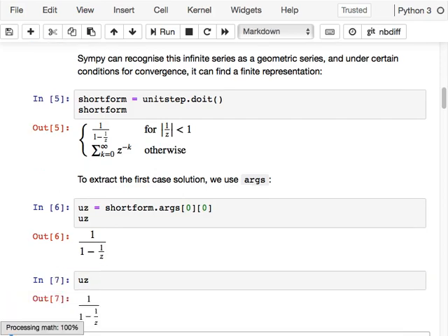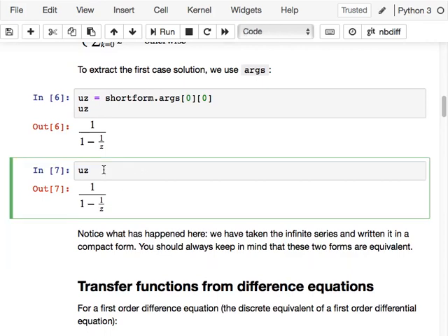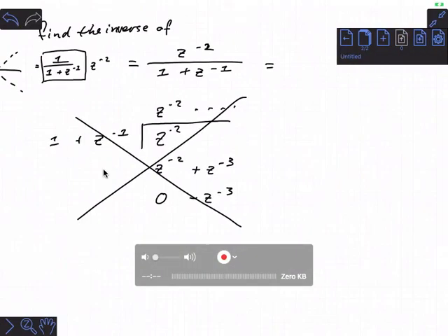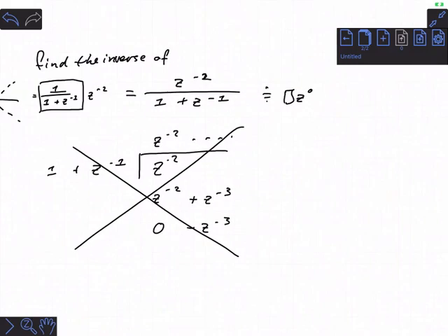so we know that this unit step that we developed yesterday will have coefficients 1, 1, 1, 1, 1, right? And so how do we get there? We can just do a series expansion, right? Because that is effectively what a Taylor series is. It's the answer of, well, what does this thing look like if I approximate it as some coefficient times z to the 0 plus some coefficient times z to the minus 1 plus some coefficient times z to the minus 2 and so on.